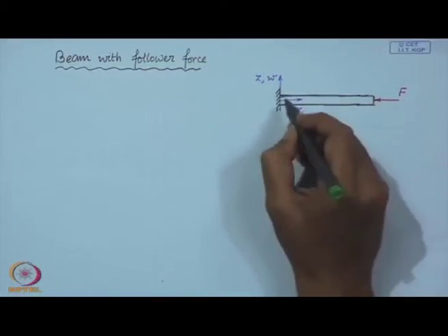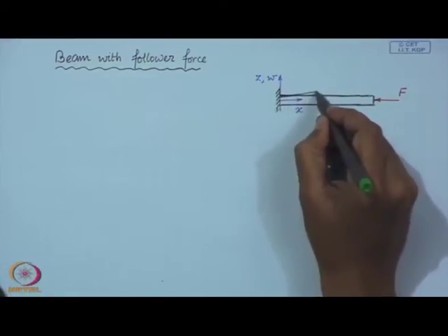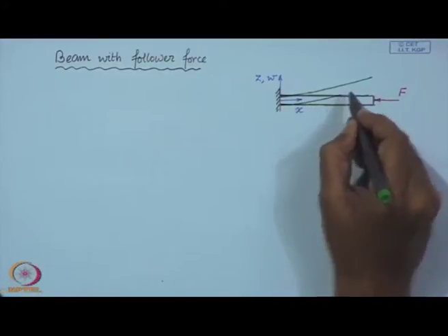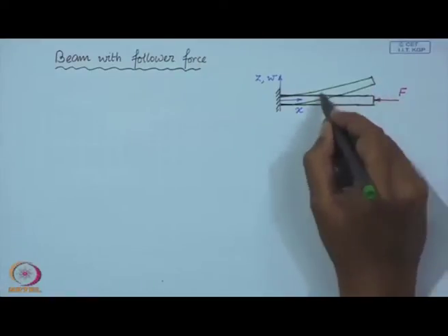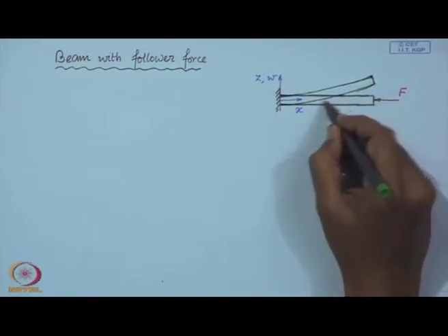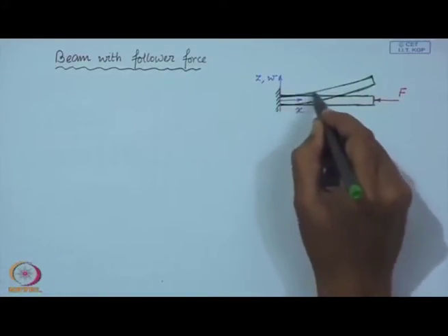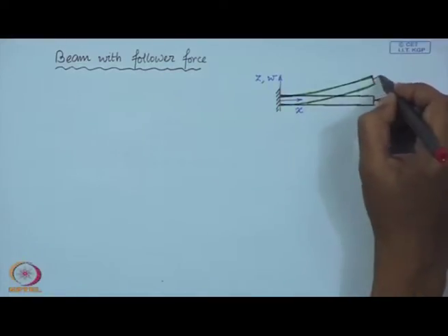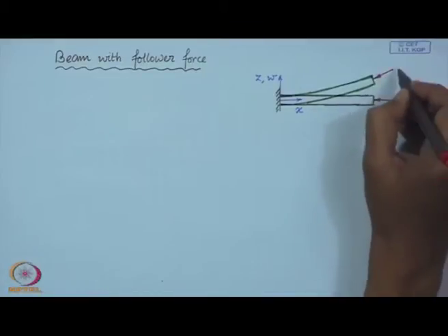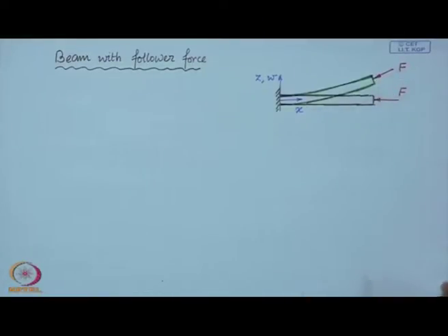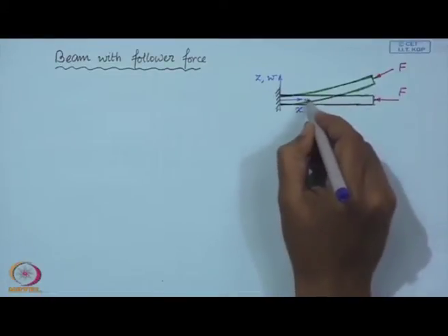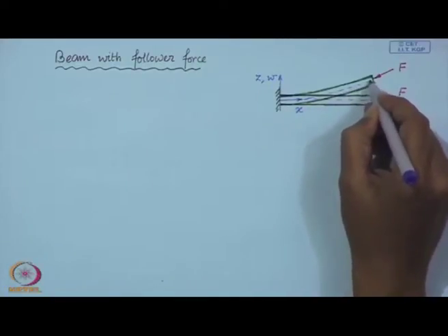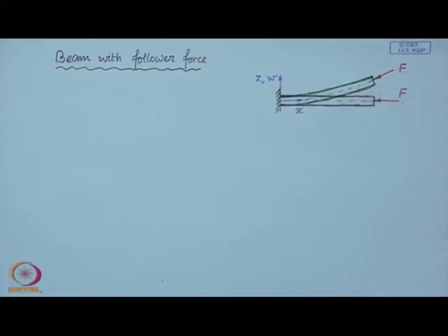But then this force has this property that when the beam deflects, so this is an exaggerated figure, the force is going to maintain the same angle as the center line of the beam.